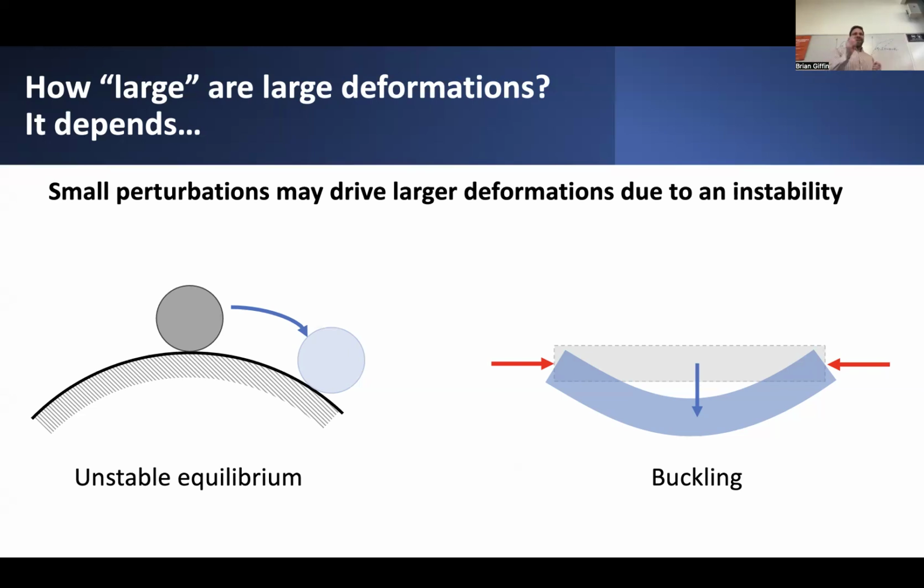And if you're doing it by hand, certainly, there are existing equations like the Euler buckling equations that take that into account. But if you're running a finite element analysis and you want to include buckling effects, then you need to include large deformation features. So turn on that toggle button within your finite element code if you want to get that to come about. But again, I want to reinforce the point that even just a small amount of deformation can lead